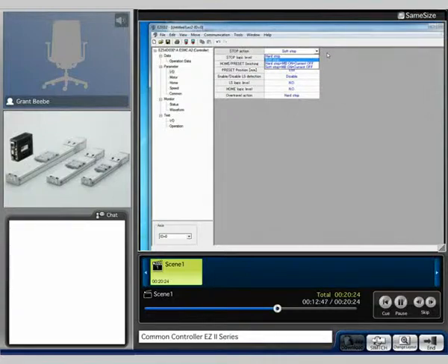And then we can turn on and off magnetic brakes if using a magnetic brake type. We can set a stop logic input level. For the home and preset, we can switch between a home or a preset. We can enable and disable limit sensor detection and also change the limit and home sensor logic levels. Upon over travel action, we can either come to a hard stop or a soft stop.